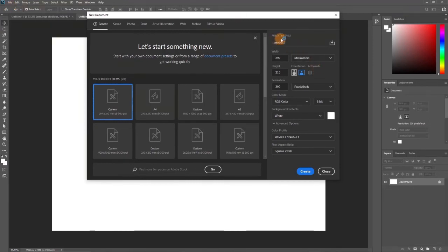The first thing you realize is preset details. In the preset details, that's where you have the size of the canvas. So we can choose to make the canvas width 500 millimeters and the height 250 millimeters. Any size of your choice is good to go. And remember, the higher the resolution, the higher the image quality. The lower the resolution, the lower the image quality. We use RGB when we are working for screen purposes, as in when the design is going to be seen only on screens. We use CMYK when we are going to print out the design. Let's stick to RGB in this case again.